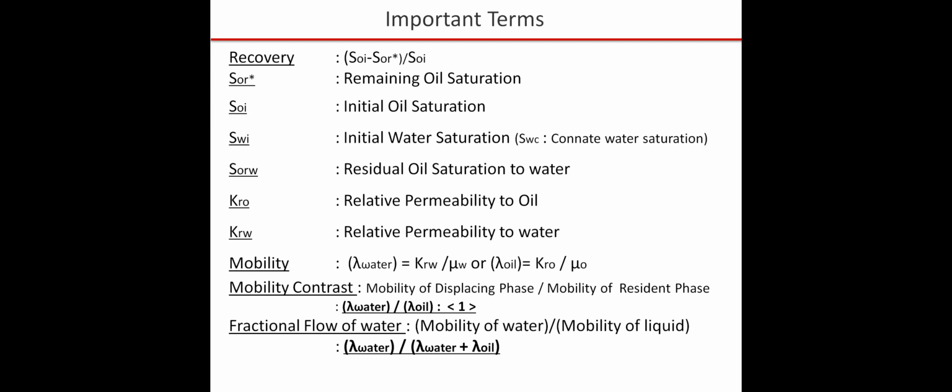And that we term as SORW, the residual oil saturation to water, when the capillary number reaches 10 to the power minus 7, beyond which water is not able to reduce the oil saturation further in the pores, when we need to do something different.